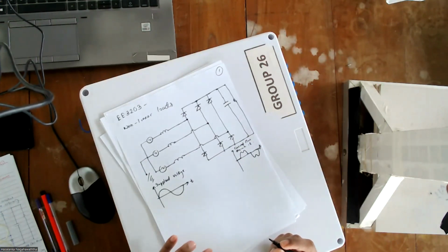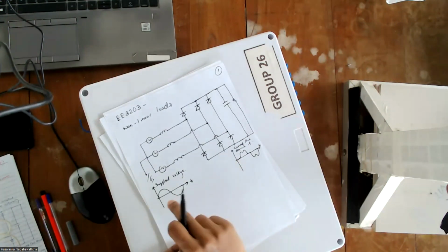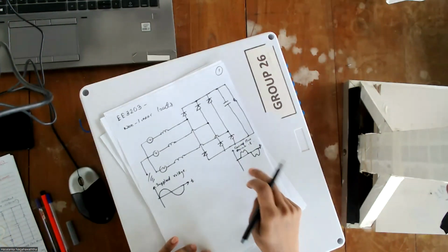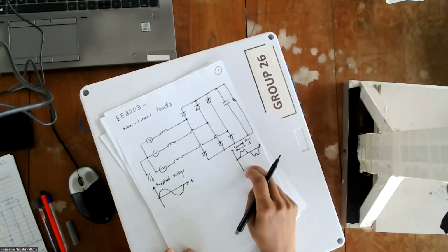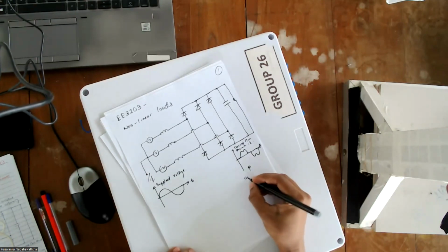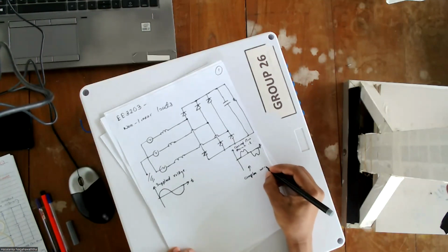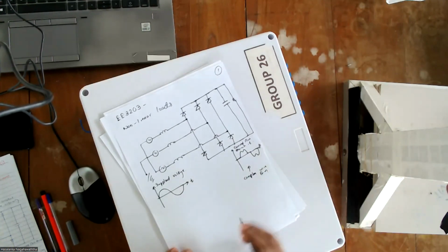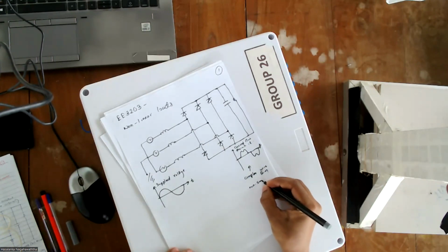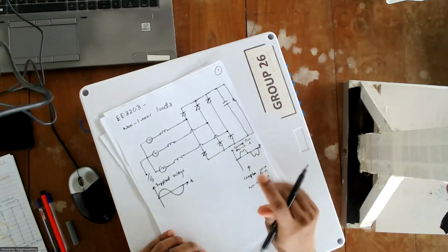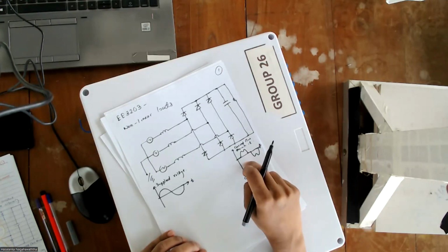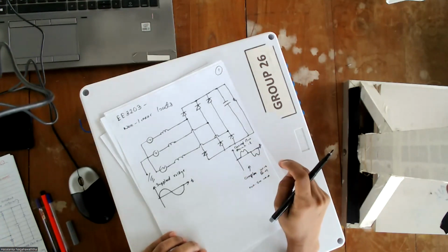So we can see the supplied voltage and the drawn current are not proportional. It is a non-sinusoidal waveform, referred to as a complex waveform. It is a non-sine wave. Therefore, this current is said to contain harmonics.